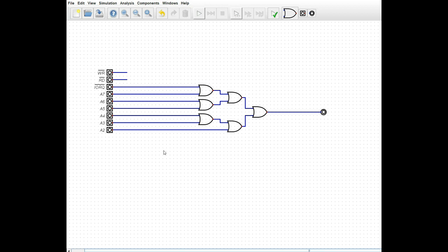Now we're also going to implement some type of FAT file system. So I know I'm going to need a chip select here, so I'm going to choose my base address for that at address C0, and that's going to give us, I think, a total of 9. I believe so. I believe it's 9. Also a keyboard. We're going to have an actual IO mapped keyboard, so we're going to stick that at location E0. So that's 9 altogether.